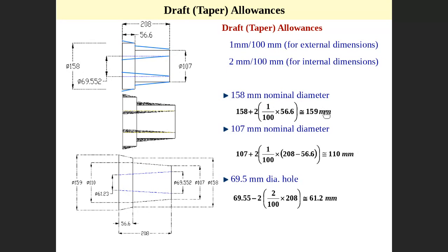Someone said that the dimension will now become very big. Okay, it's safer, because if you do the casting process and the dimension ends up smaller than what is needed, then it is scrap. We need to avoid having scrap. Someone will also ask me, we have a riser, and this riser usually delivers liquid to compensate for shrinkage and so on. This is for more safety.